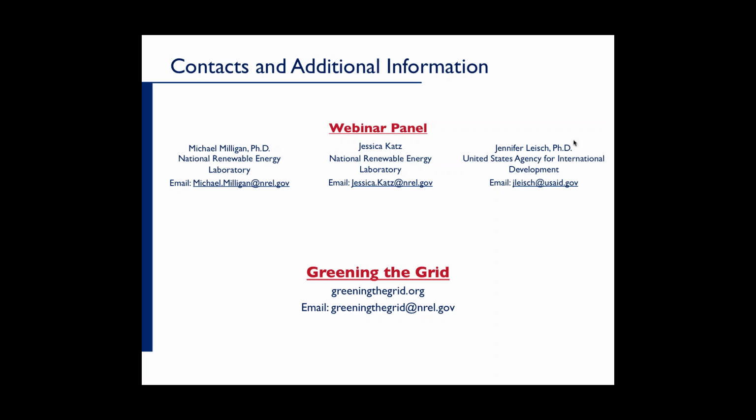We can look at that by taking the annual hourly demand and then say, let's imagine that wind and solar is built in these capacities at these locations, and we can look at the same kind of curve that I showed you early on in the presentation that shows the demand by itself, and then we subtract off the wind and solar, and we can see what sort of flexibility is needed in the remaining part of the fleet.